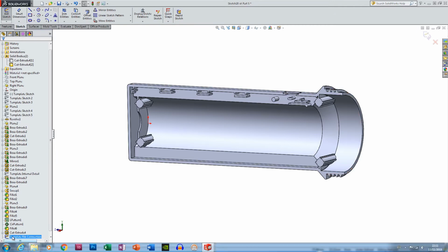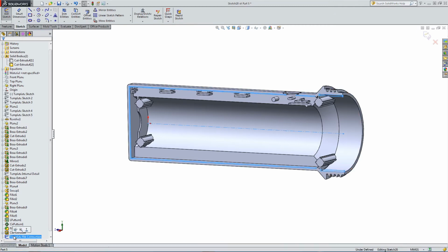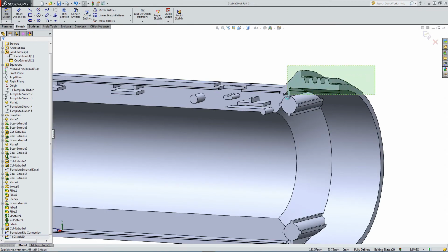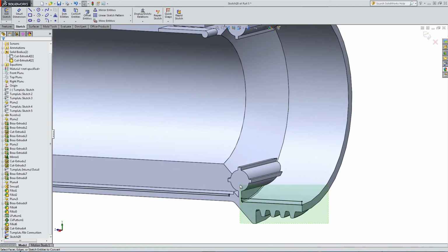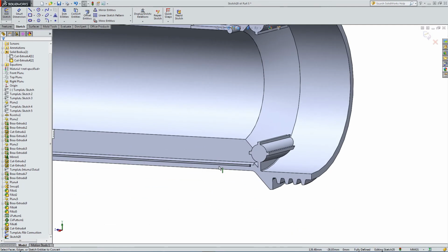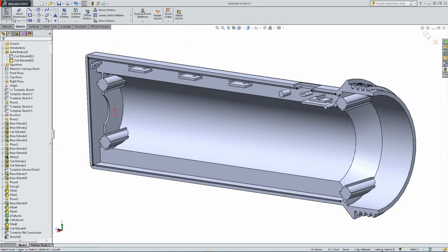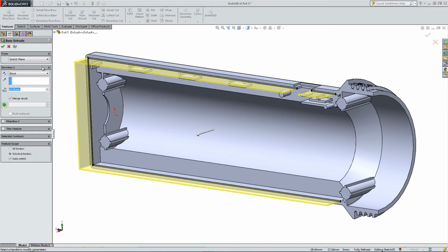So our two plastic parts, basically, they're going to come together. But they could slip and slide. So if you have some interlocking ribs, you can guarantee that one part falls over the other part. And it also means that grease and grime won't get between the two parts and get through the gap.